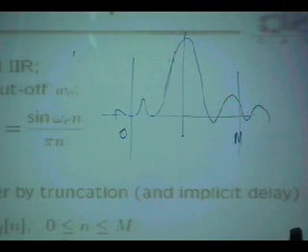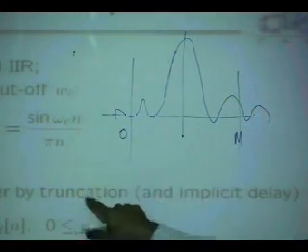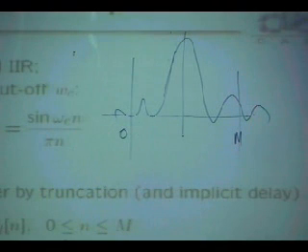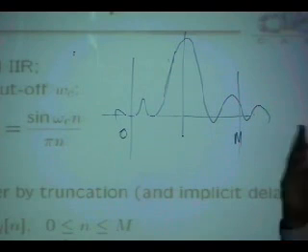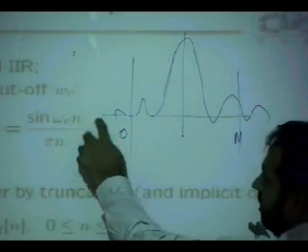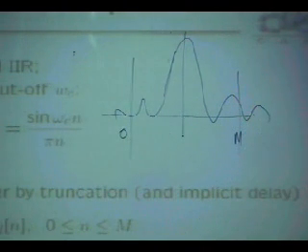So you make it causal, and we have seen type 1, type 2, type 3, type 4 filters. Those all filters represent a delayed version of this. Remember the n minus 2 alpha. It could be n minus 4.5, it could be n minus an integer number. So two possibilities: once you shift it, it is n minus an integer or n minus an integer plus 0.5. So both will result in a symmetric filter. This we covered. So let's go on.